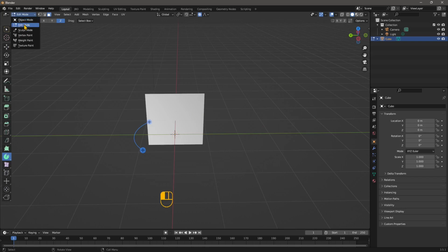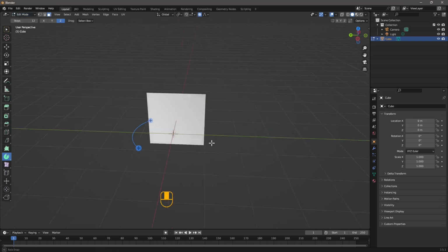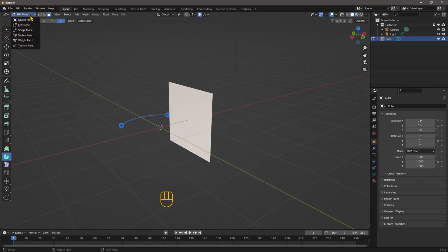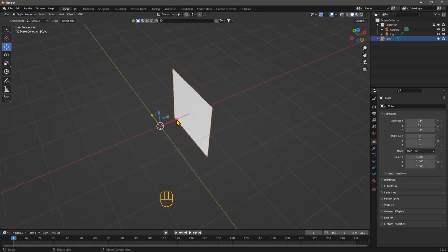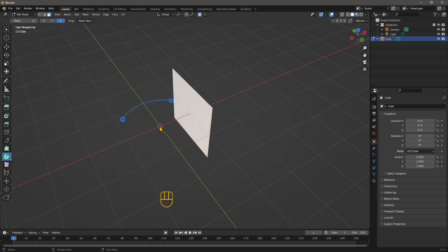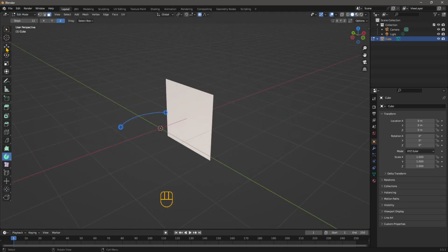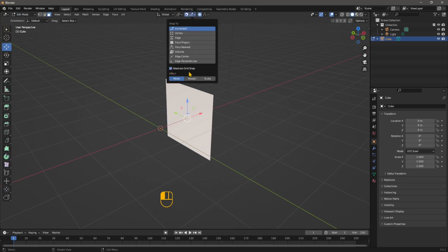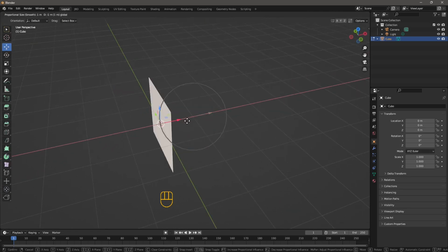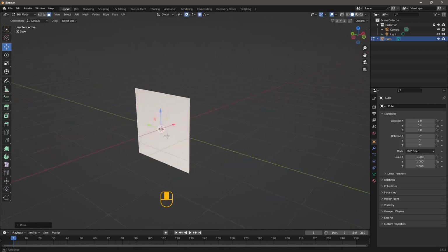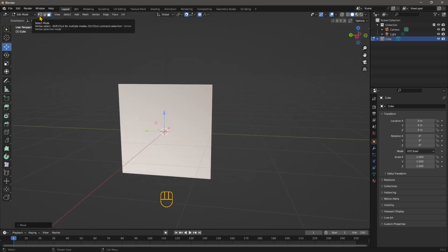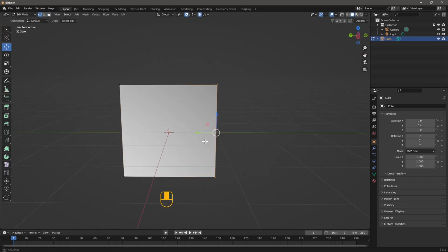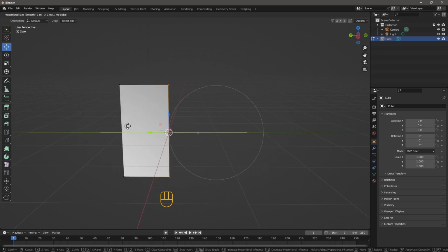So what I'm gonna do is stay here in edit mode, or actually go back to object mode. But make sure that you have this face at the origin. So we're gonna use move, and we're gonna also use the snap to the absolute grid. So when I move this, I will move it precisely there. And then let's go into the editing of the points. So I'm gonna take these 2 points and I'm gonna move them right here. You can see it's snapping to the grid.